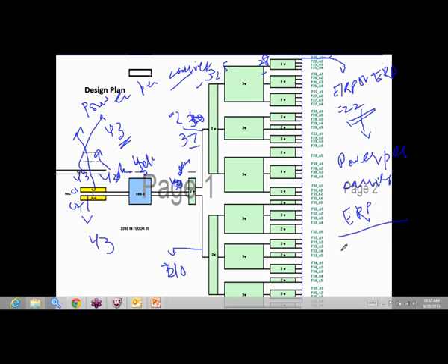Power per carrier is also called power per channel. Okay, so we can also call this power per channel. Remember this, power per channel. The reason this is power per channel is because we started our calculation, we took this 43 dBm, which is the total power of this carrier 1 or C1. So since we started our calculation on the basis of complete power, this is called power per channel or power per carrier ERP. So the calculation we did for ERP or EIRP was based on power per channel or power per carrier. iBwave calls it power per channel.